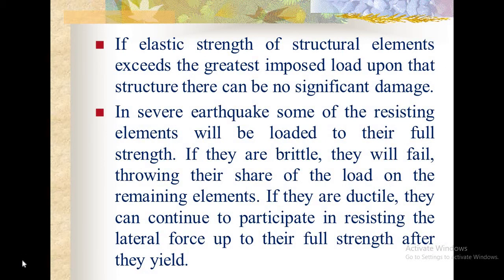If the elastic strength of the structural elements exceeds the greatest imposed load upon that structure, there can be no significant damage. In a severe earthquake, some of the resisting elements will be loaded to their full strength. If they are brittle, they will fail, throwing their share of load on the remaining elements. If they are ductile, they can continue to participate in resisting the lateral forces up to their full strength after they yield.